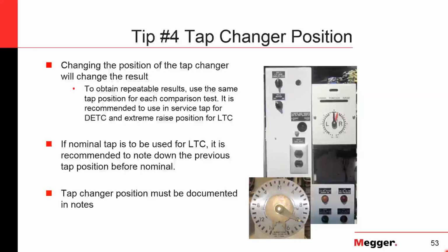When you do SFRA, you will see that in the factory, the SFRA test will be done somewhere close to 20 degrees C at ambient temperature. Then in the field, if you are running your test between, I would say, 10 degrees and maybe 30 degrees, the influence of temperature is really minor. But if you go beyond that, the effect is more on the resistive component of your winding. So yes, we have seen the influence of temperature, and we have seen small deviation, especially on the open circuit test, especially on the very low frequencies of that. If we think just from the physics of the materials, it is a resistance, and the resistivity will be affected by temperature.